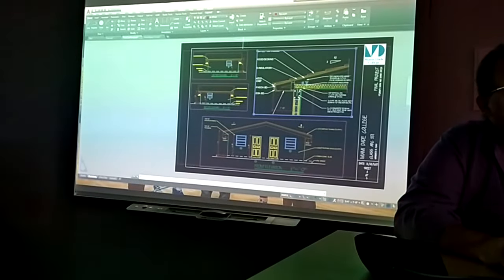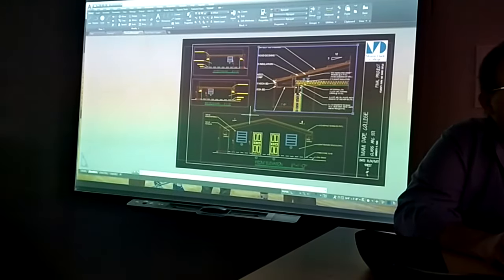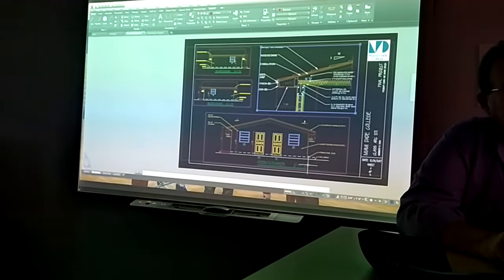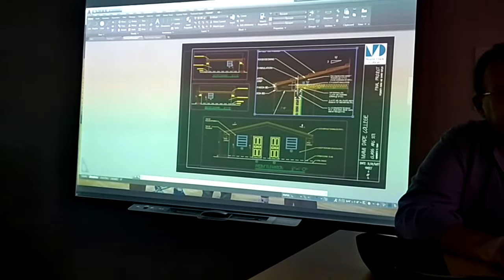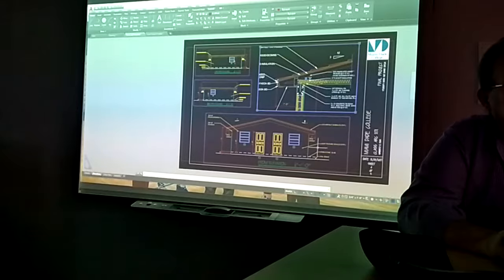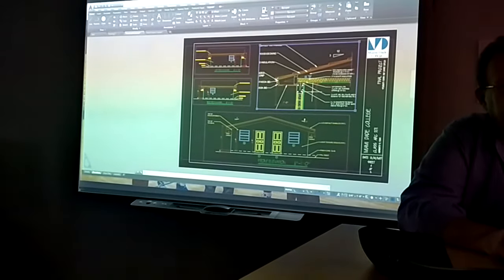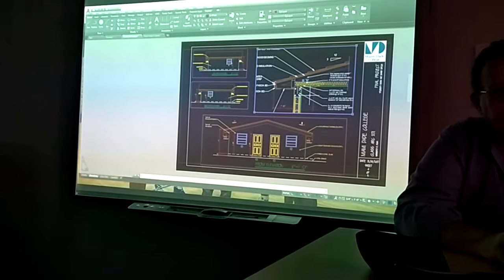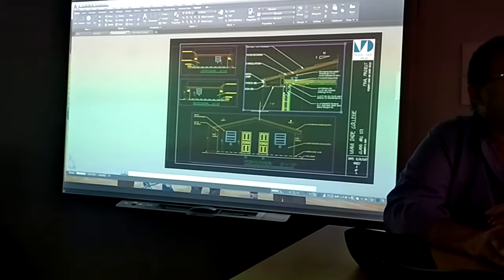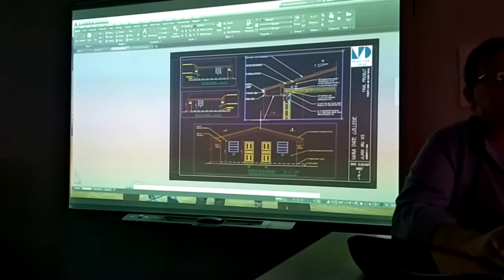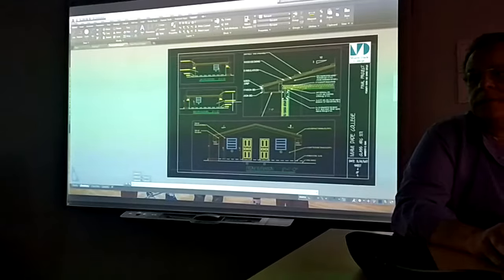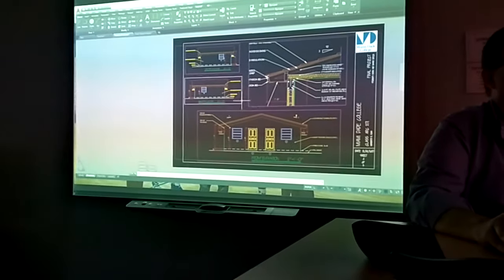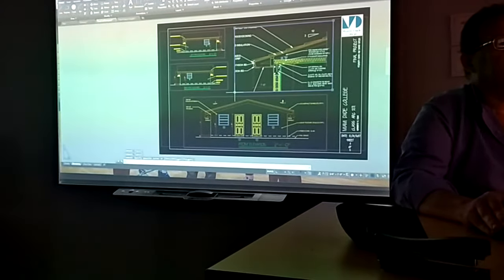I wouldn't recommend match property from here to there because then you're gonna mess it up. Because here you've got one drawing and one scale, and this is another scale. Otherwise this scale becomes the same as this one. If you match property, don't do that. It's a no-no. Do you know no-no in Italian? You know, grandfather? No-no? Well, it's a no-no.